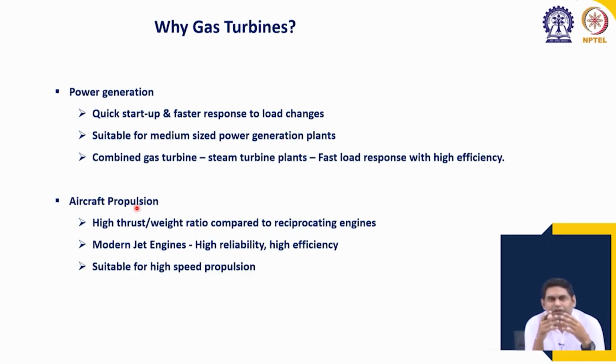Inherently the power delivery is not rotary in nature. So, converting it to rotary motion involves some balancing issues. Then there are also issues with the mounting of the propeller. The engine has to be mounted towards the front of the aircraft, not at the middle of the aircraft, which also causes control issues, right, maneuverability issues can be there. And then